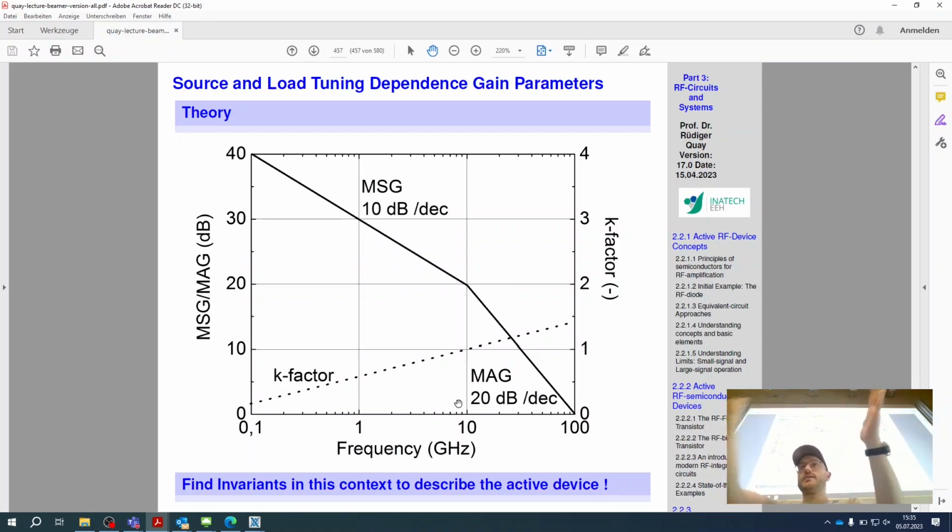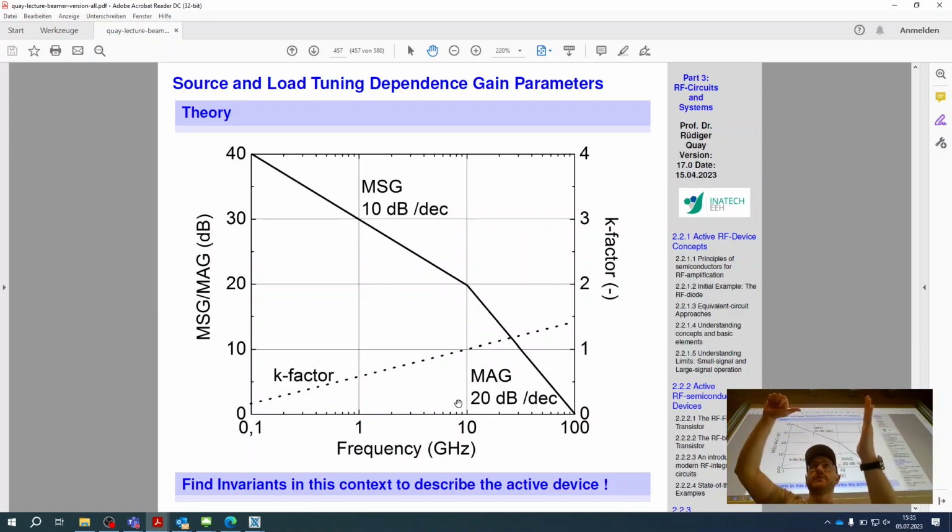It gets re-amplified, gets pushed back to the outside, and gets reflected from the outside, because you have a certain mismatch in load, so that only 10% of your energy gets transmitted to the outside, but the rest gets reflected back, and so forth. So you have this point where you're ringing, you have a standing wave which just amplifies in amplitude, and once it reaches a certain amplitude, it burns out your device. The K factor is just a means of plotting whether this happens.